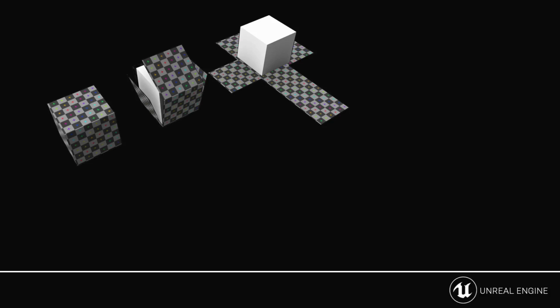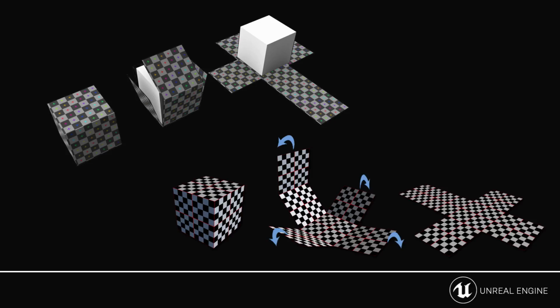So this process of UVs, how does it work? Well, here's a simple illustration here. You have a simple cube and this idea of unfolding this or unwrapping it, or maybe a simpler way to look at it here is in this checkered pattern down below, where we are essentially unfolding and flattening this out into something that allows us to place texture detail onto a flattened, opened, unwrapped, this idea of a pelted version of the 3D mesh to place that texture detail on there. So an overview of UVs.